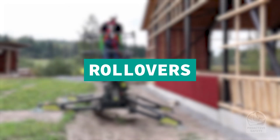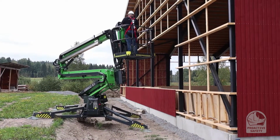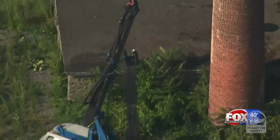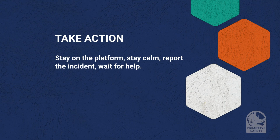Rollovers. The risks: unstable center of gravity, uneven terrain, and high winds. Example, an operator exceeded the load capacity, causing a rollover. Take action by staying on the platform, staying calm, reporting the incident, and waiting for help.